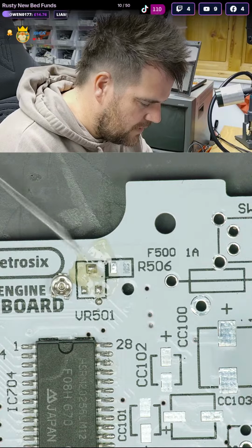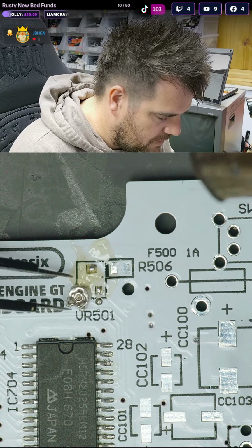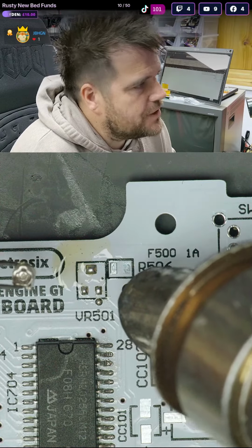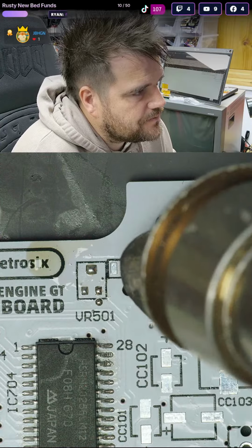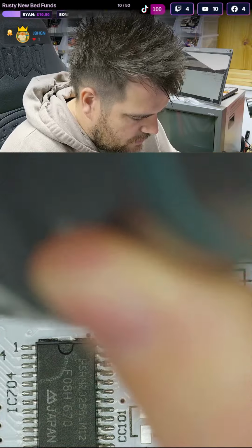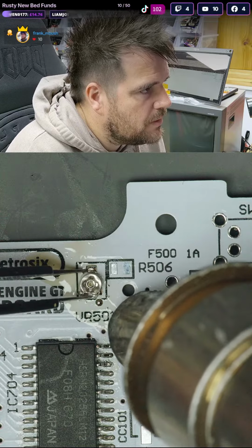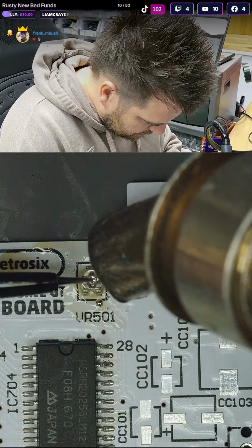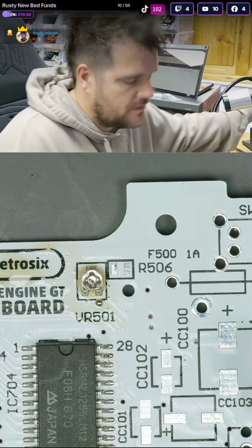Boiling solder. So now, if we've got that on, we can hot air this on. If you're going to hot air these on though, I tend to, just because these are some things that can be sensitive to heat, warm the pads up first, and then you're going to have a temperature difference between the component and the pads, but that's fine. Warm them pads up, try and blow that flux back over while we're doing it. That's it, and now the pads are liquidus. Plonk the pot on and nudge it into position. A little tap down, and that's the potentiometer in position.